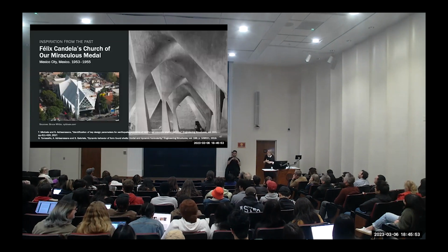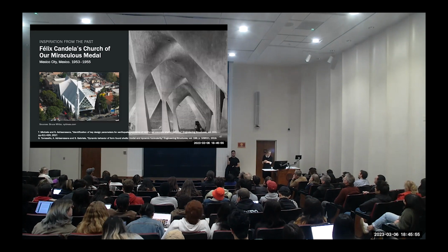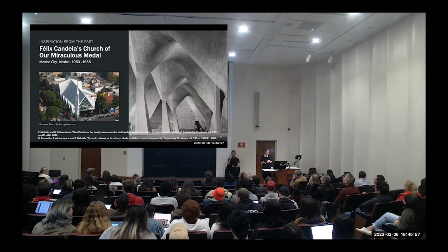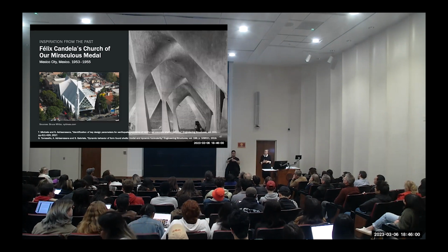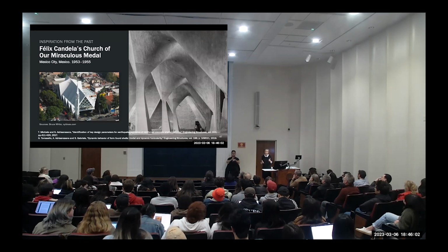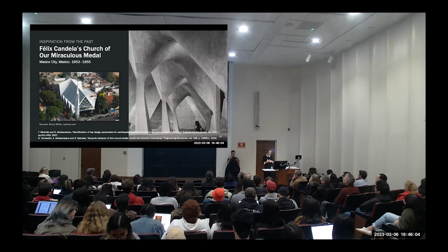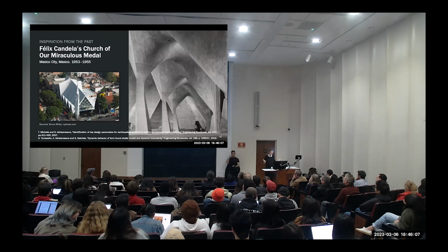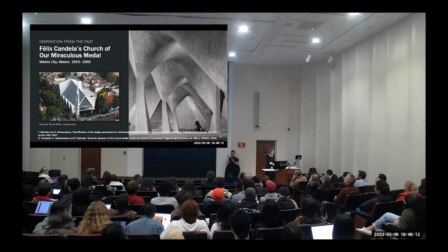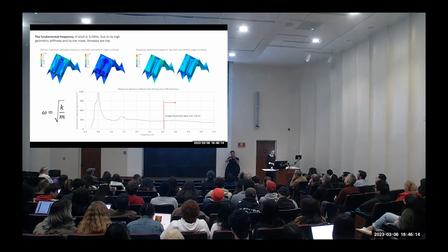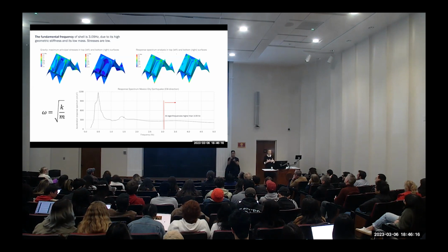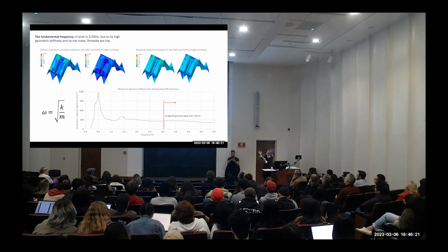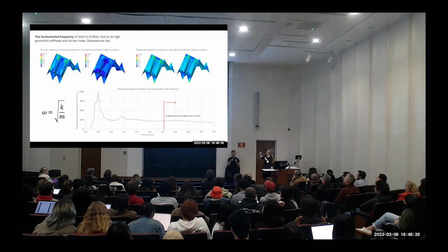So we took this shell as our case study. This is Felix Candela's Church of Our Miraculous Medal in Mexico. This church stood in 1985, when there was a huge earthquake in Mexico, with a magnitude of 8. We took this geometry and carried out all kinds of analysis to study what the forces are under that earthquake, and what we see is that the stresses are all quite low. But the thing that was very surprising is when we looked at what we call the eigenfrequency.